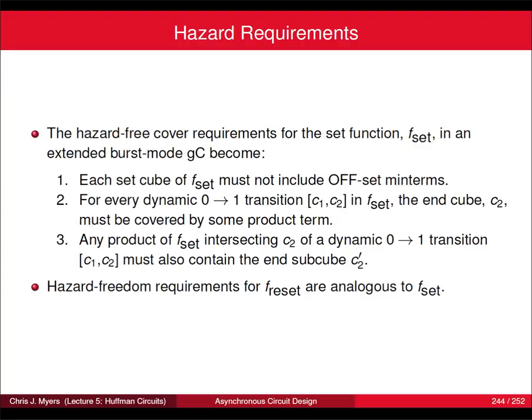So what do you need to worry about? The hazard-free cover requirements for the set function in an extended burst mode GC are as follows. Each set cube of your set function should not include offset terms, which makes sense: you're trying to set it, so your set cube shouldn't be on in the offset. For every dynamic 0 to 1 transition, you have a transition cube C1, C2 in F set.